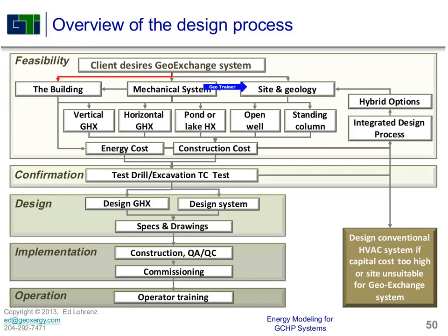We can start doing some things, depending on how much land area we've got, by looking at hybrid options with gas auxiliary boilers, auxiliary cooling towers, or whatever else. But where we can have the single biggest impact is this. We can have virtually no impact on here except minor impacts on the detailed design of the ground heat exchanger: borehole spacing, high thermal conductivity grout, things like that. Changing the diameter of the borehole, adding an extra U-tube, putting coaxial heat exchangers in there.